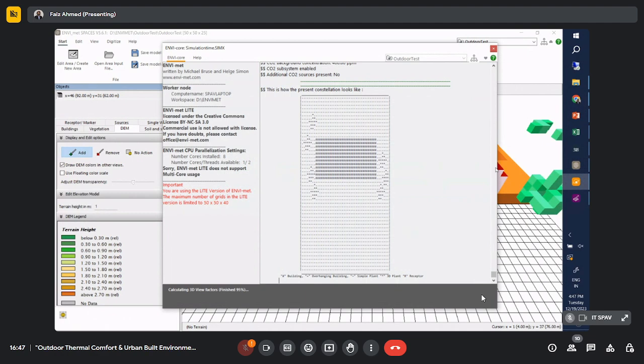Probably in due course, in the next 3 days, you can create your model. Create a smaller version, and then try to run at least one simulation to understand whether you are able to run it. You may encounter problems. To start with, I think we can start with the EPW file, and then you can do simple forcing and then run the model. That'd be easier.